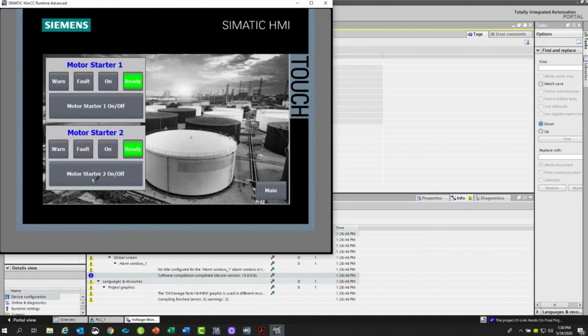A lot of times what I'll do is marry that with your traditional starter, and I'll put that current monitoring relay below it. Or for retrofit applications, I'll put the current monitoring relay with this standalone shoe and be able to retrofit that right below the existing contactors with the system.